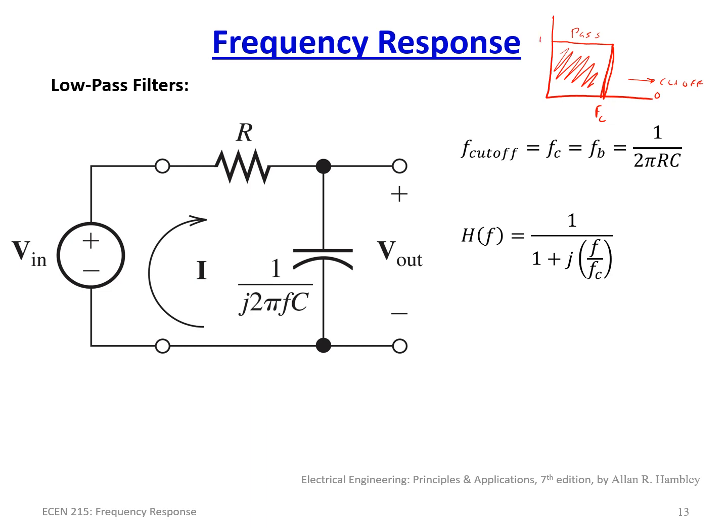And we'll just put a 1 here that is just cutting through. So the idea is, another phrase for this is also known as FB, or the break frequency. There are different conventions. I think the book might use FB. I usually use FC for cutoff. That's more common. So you have that, and this is simply 1 over 2 pi RC. In other words, the time constant of the function. That is the cutoff frequency.